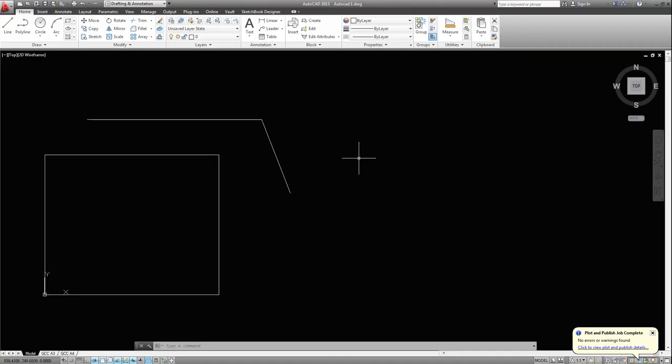So that's something to remember. It's really important to remember. Left to right, you've got to cover everything. Right to left, it selects everything it touches.